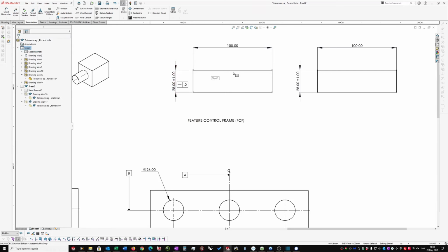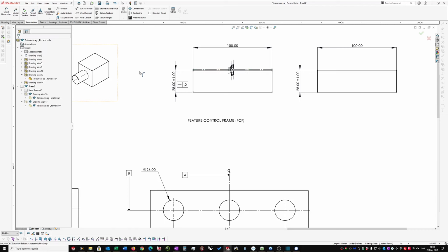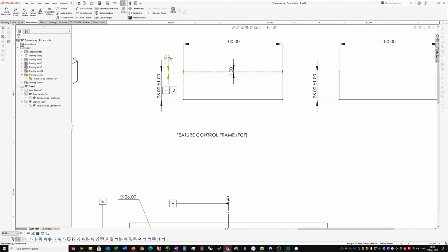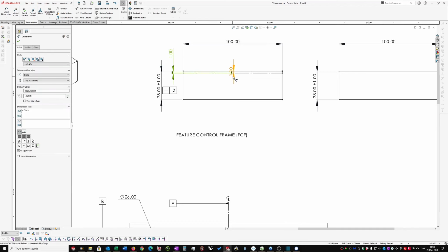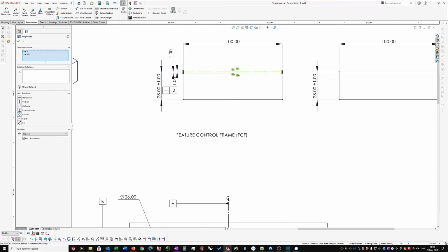By offsetting just this line. Just do that again. Offset that line. I want it to go bidirectionally, and I want it to be construction geometry. Okay, and it says plus or minus 1, so that's got 1 millimeter in there. So it could be 27 or 29. Just to make this a little bit easier to understand, let's color these. Let's make those a bright blue, and make them a little bit thinner as well.